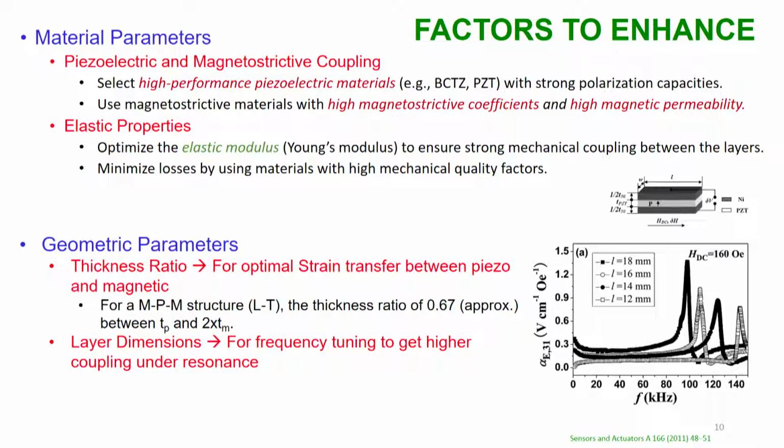They will only use the standard one and then try to improve, reduce the noise and increase the sensitivity. So here you have to look at the piezo and magnetostrictive coupling coefficients, or the coupling nature of that. You need to have very high magnetostriction with high magnetic permeability. This is mainly because, as I mentioned, you are giving H externally, but internally, in order to do everything, you are going to have a B.